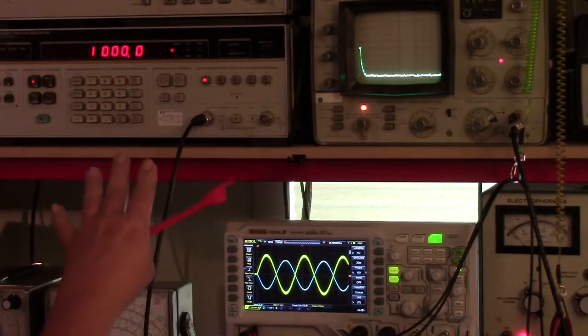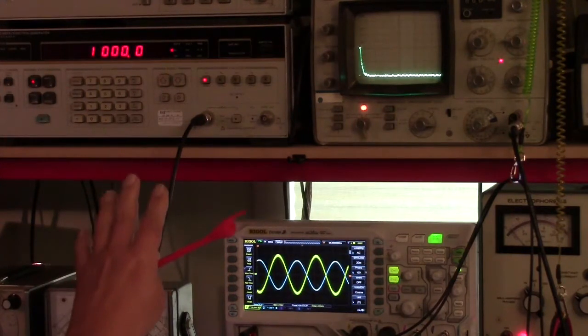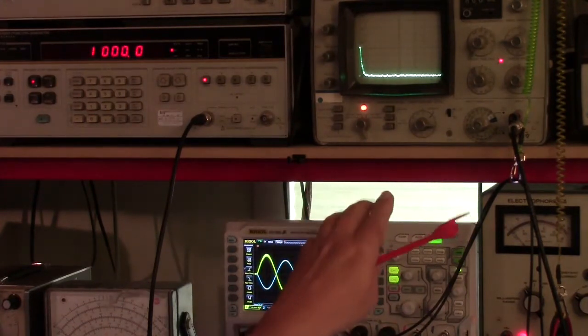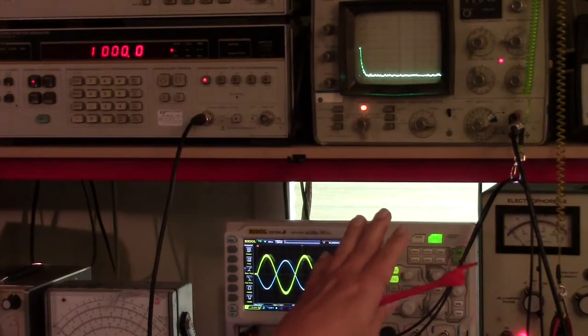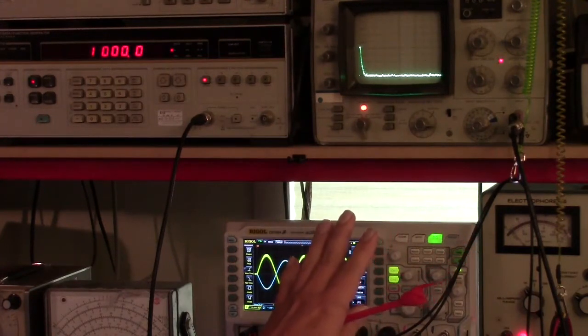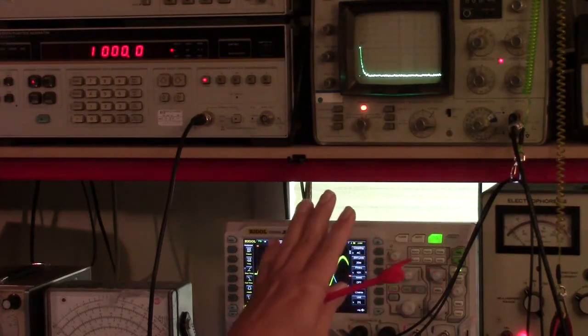Up here, I'm driving it from an AC perspective. I have a function generator, and I have it properly terminated. I'm coming out on a coax here, and I have a 50 ohm termination resistor right down next to the guitar amplifier's input jack. And then over here I have an HP spectrum analyzer. We'll go ahead and show you some spectrum of the waveform once we run it up, and show you distortion characteristics.